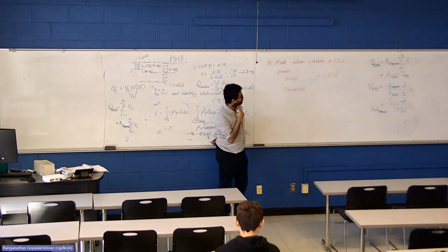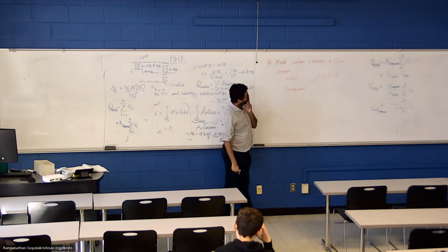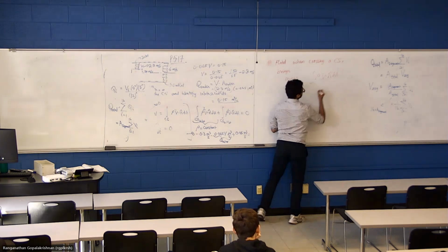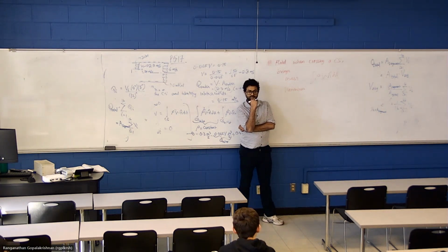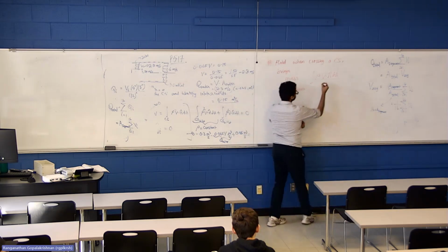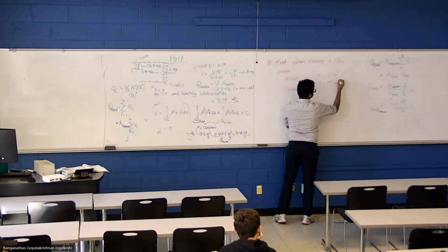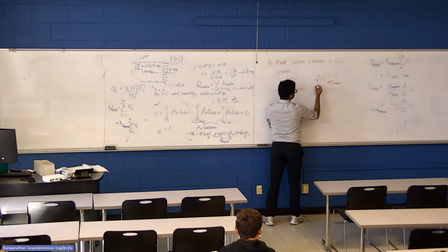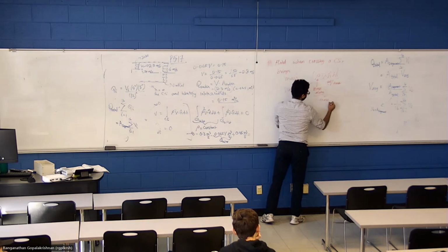How do we write an expression for momentum that the fluid brings due to its velocity? What is this quantity? What are the units of this quantity? Volume flow rate. This is volume per time. Right? So by taking volume per time and multiplying with mass per volume, you are getting mass per time.